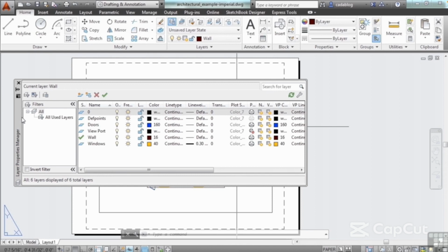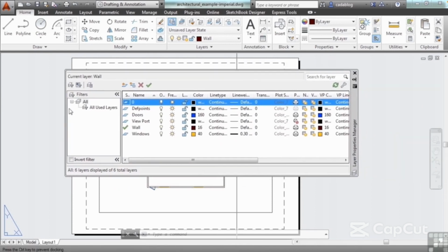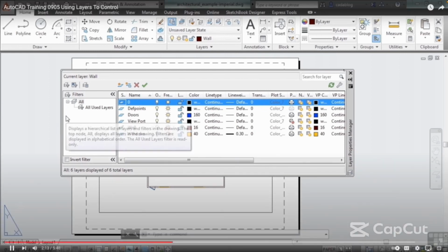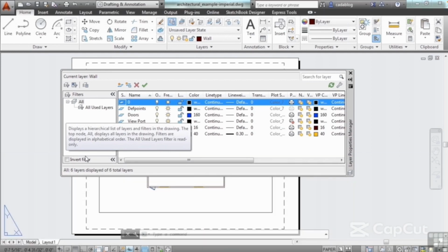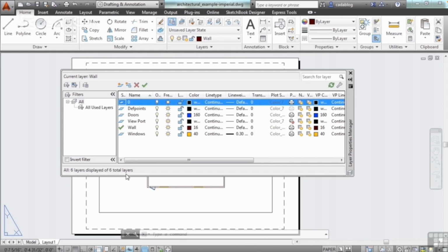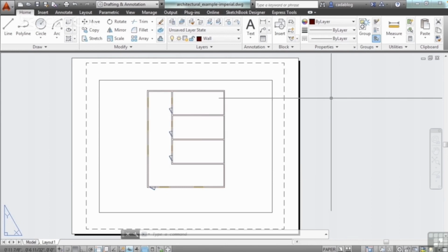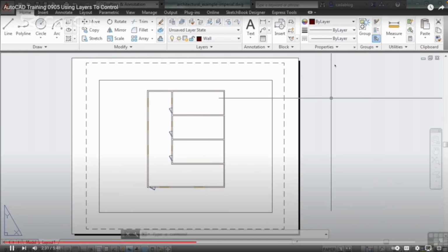We only want to change the objects, though, in a specific part of our drawing. We can make a detailed view of any part of our window here, of one of our doors, or a combination of a wall joint or anything. And so sometimes, though, you want to make other things faded back or to be dashed or not shown at all. And that's okay. You don't want to have to make a new file for all of that. You can do that right here. To do that, you have to edit the layers while in an activated viewport. Since these are all drawn to by layer, we can make the change here.